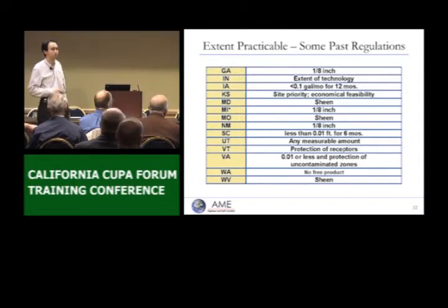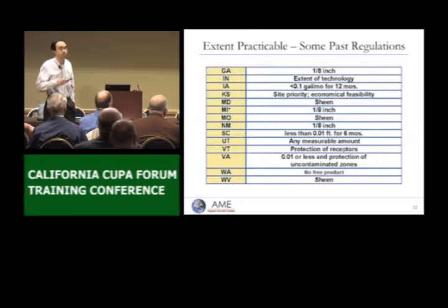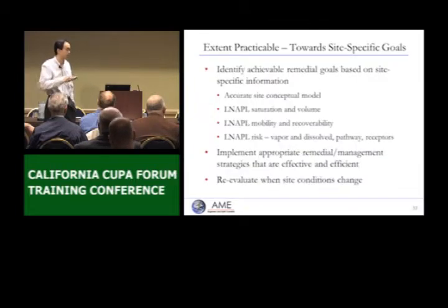Site-specific goals. We already have some progress in that. California, in my opinion, is quite stringent, but they do have this low-risk groundwater sites policy for USTs, based on all the studies that say petroleum hydrocarbon is going to be naturally attenuated. So if at some location you don't have a receptor, you don't have an exposure pathway, you can close it before the concentration reaches a certain state limit or the drinking water level, whatever. So that's a good thing.